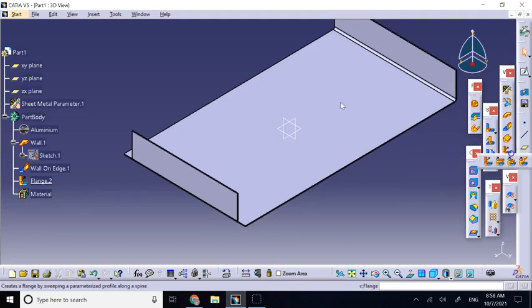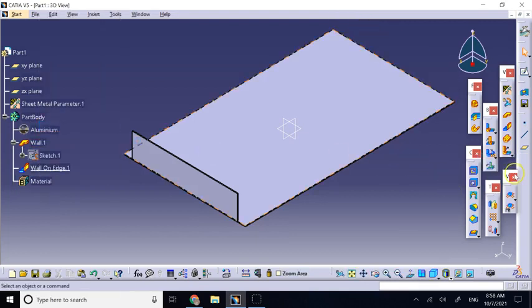If you expand the flange, there is hem, there is a teardrop, there is user flange, and so on. And the most common one is a hem. So hem is not like direction bending in just one direction. It's actually two bendings, or a U-shaped bending, right? So let me show you that one instead of this flange for now, and then I'll show you more stuff.